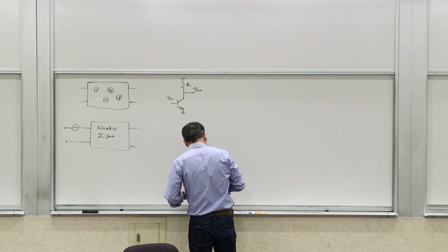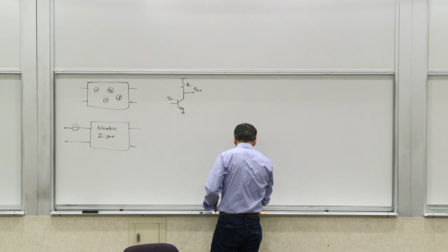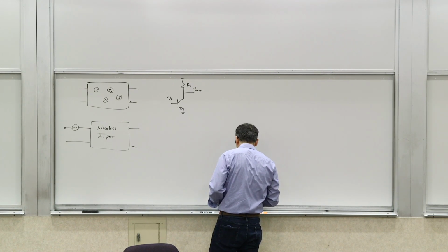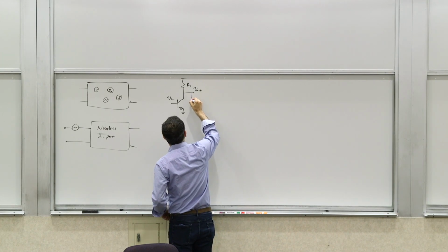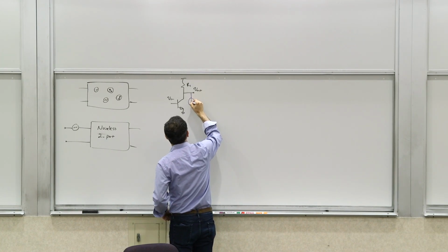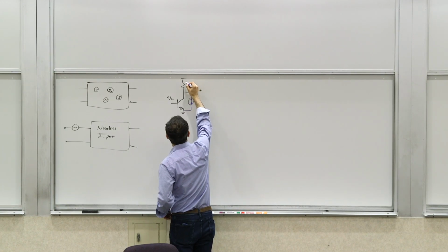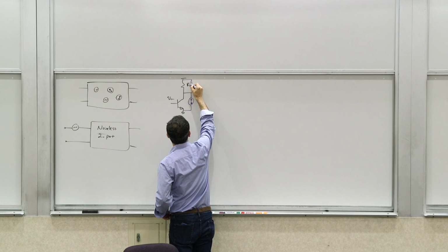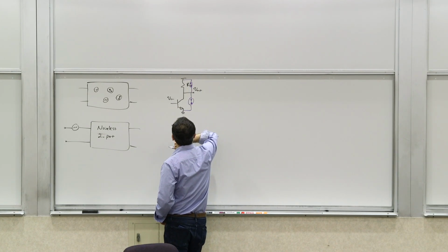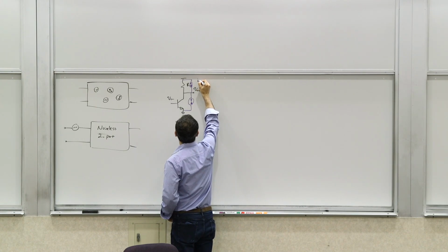And what are the noise sources, right? So let's just talk about a couple of noise sources to make things relatively straightforward, so we don't make our lives too complicated. So let's look at the collector shot noise for this discussion. And let's look at the thermal noise, Johnson noise, of the R1. So we know this noise as a current source.